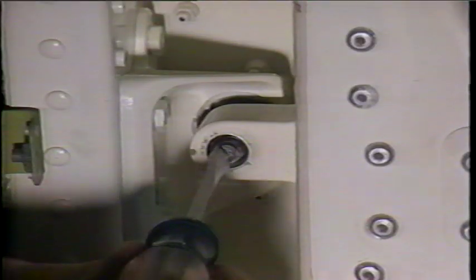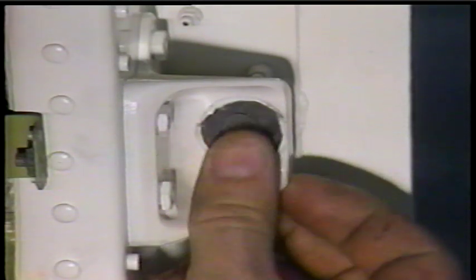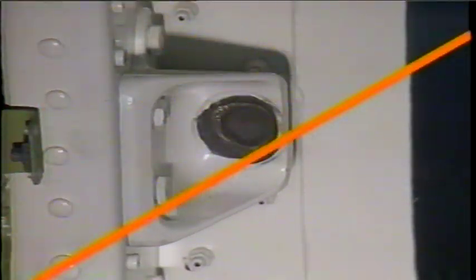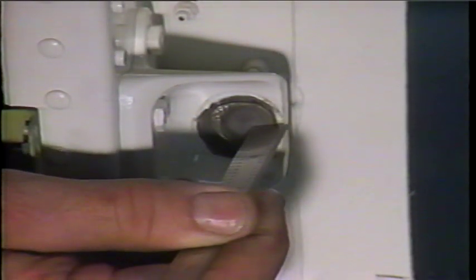Open the door. Lightly coat the stop pins with Vaseline or similar grease. Place modeling clay on all stop pads. Close and latch the door, then open the door. Check that the thickness of the modeling clay at the stop pin impression is per the maintenance manual. Rotate the stop pins as needed to get the correct thickness of modeling clay at the impression. Repeat this step as needed after each stop pin adjustment.